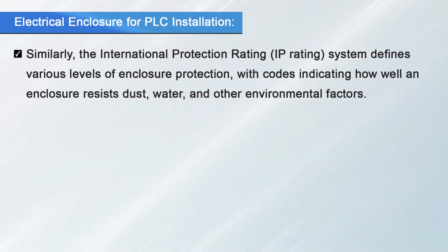Industrial electrical enclosures must meet international standards that ensure appropriate protection for both the equipment and personnel. For instance, the National Electrical Manufacturers Association, called NEMA, specifies enclosure type 12 for electronic control devices, which provides protection against access to hazardous parts and guards against solid foreign objects like dust and lint, as well as light water splashes.